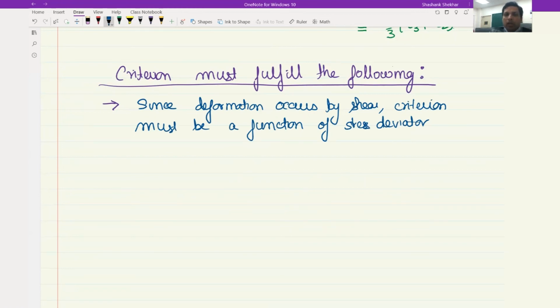So the stress deviator represents the overall stress state in terms of shear stresses alone. And we know that this is what will cause the plastic deformation, not the mean stresses. In fact, we have given that example that if you change the mean stress either plus or minus, it does not change the yielding condition. So the only component of the stress state which will define the yielding is the deviator. Therefore, we can now say that F as a function of sigma 2 minus sigma 3